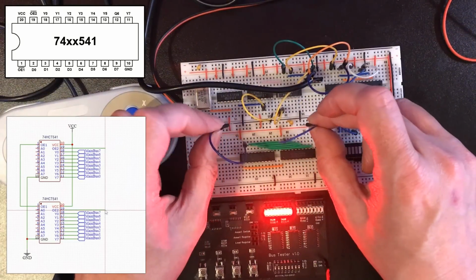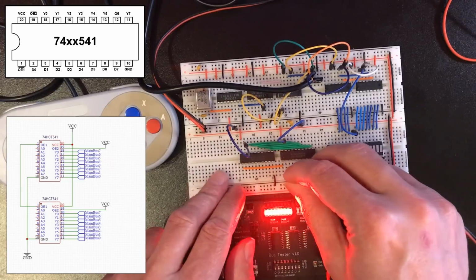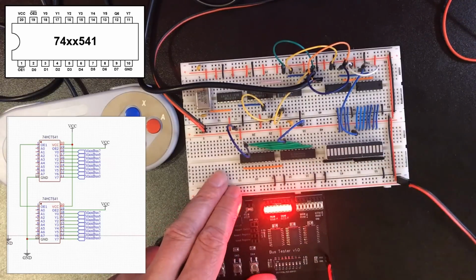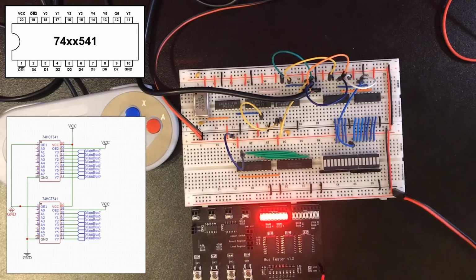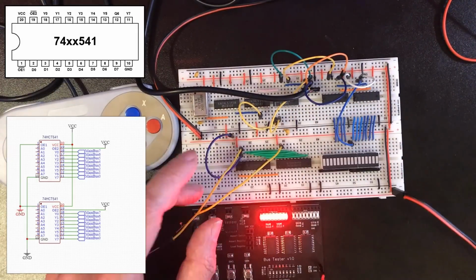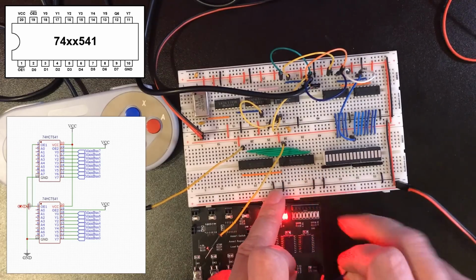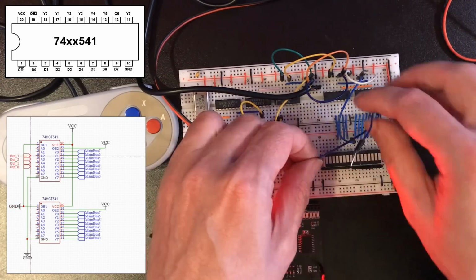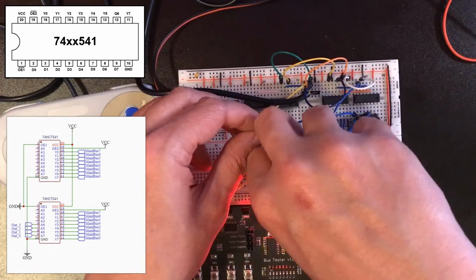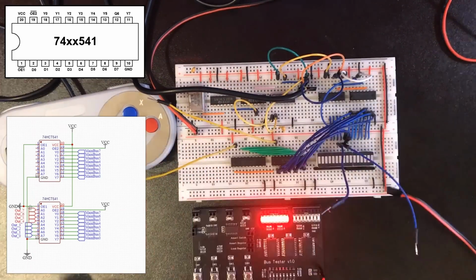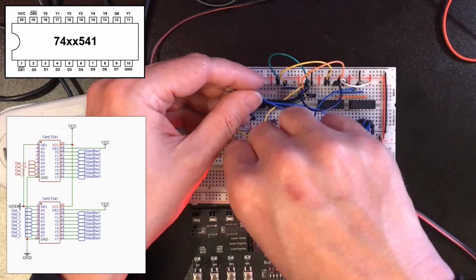So then the other output enable lines I'm going to tie high, and for now I'm going to make the lower ones low. These are active low enable lines. Actually, go yellow for these. Okay, so the first 8 lines we want to bring out to the inputs on this right hand line driver. And the next 4 I'll bring across to the second one.